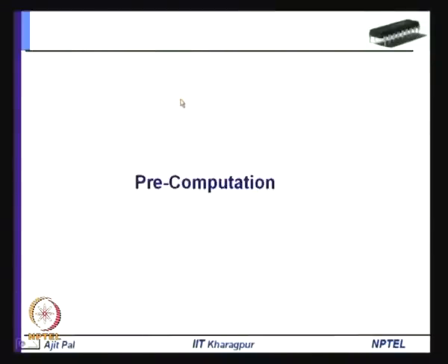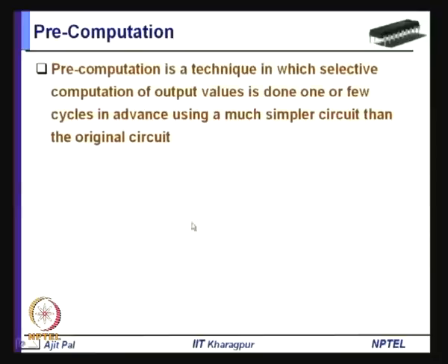Now, we shall consider another very interesting technique, that is called pre-computation. Pre-computation is a technique where selective computation of the output values is done one or few cycles in advance using a much simpler circuit than the original circuit. Your original circuit may be performing a very complex operation, say multiplication of n bits, addition of n bits, or something more complex.